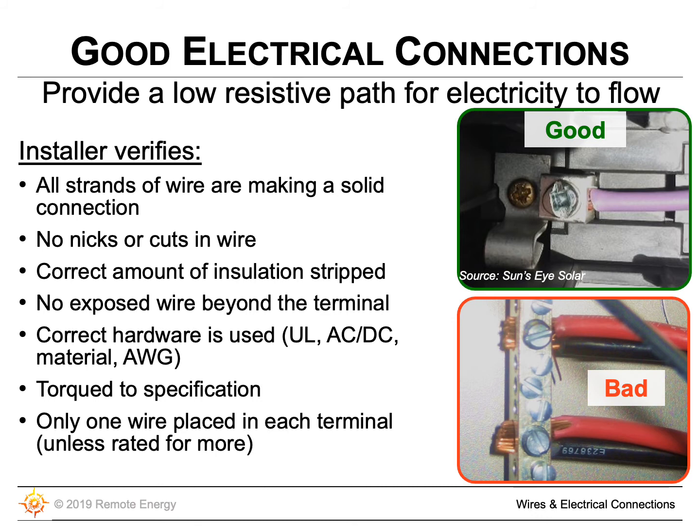We also want to make sure that it's torqued down with your screwdriver to the specifications that's in your panel board. And then also we want to make sure that we're doing the connection in the right way and that we're not putting two conductors of different diameters under the same screw.